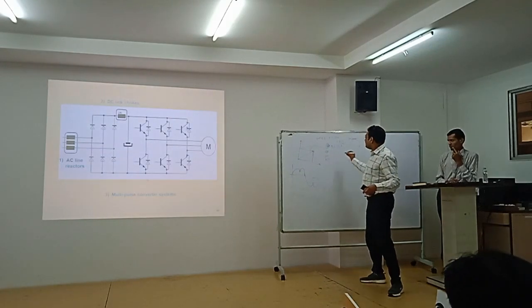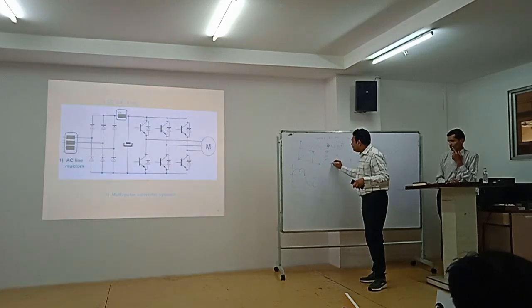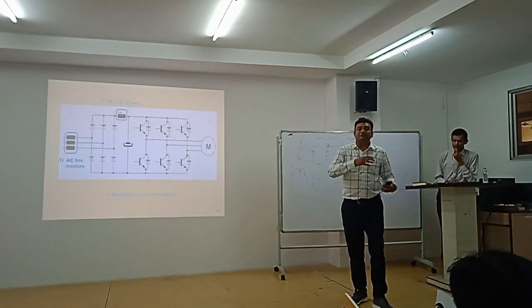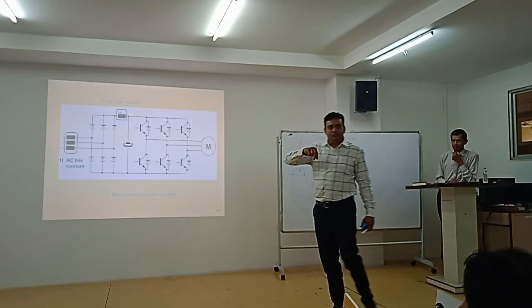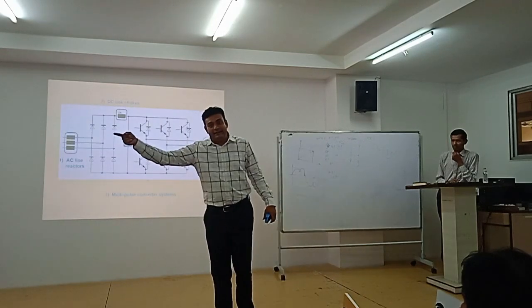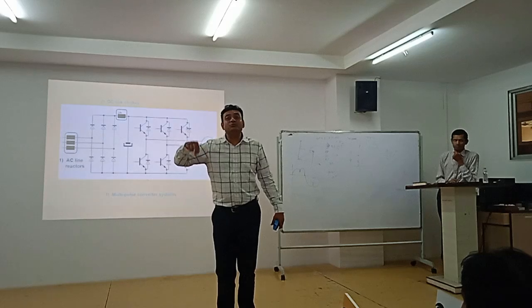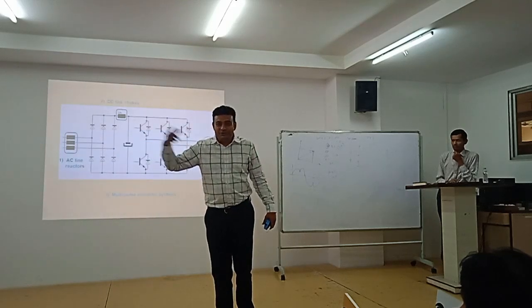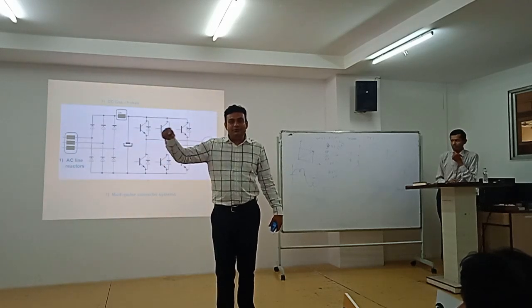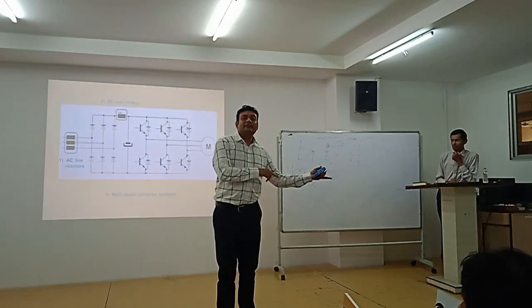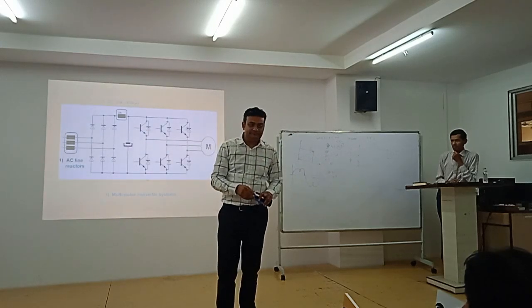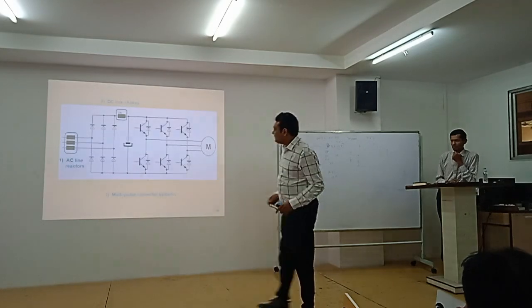If you go for 12 pulse and k equal to 1, naturally it is 12 plus or minus 1, so the 13th and 11th harmonics. The third, fifth and seventh are shifted out, and higher ones appear. So there are 2 advantages. As you go on increasing the number of pulses on the DC side, the DC is going to be smoother, which we desire. That is one advantage. The second advantage is we can control harmonics on the AC side. Okay, next.